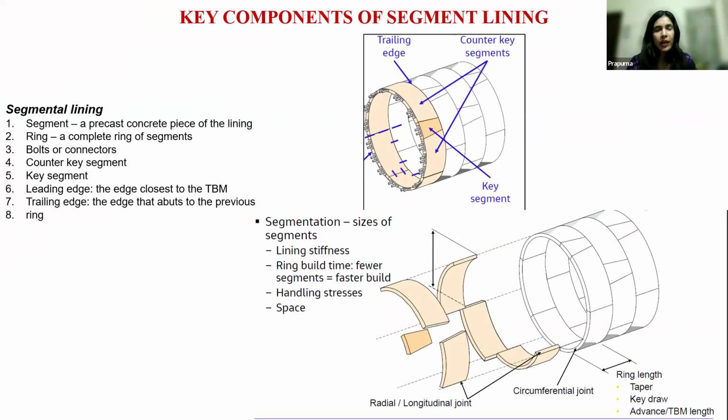Have we used hyperbaric intervention in Indian projects? We use it, but it depends, as I told you earlier. Hyperbaric intervention in Ahmedabad Metro we used in one of the stages, because in that space the ground was very soft. The clay was highly compressible, and we had very high water ingress. And in one scenario, we did the intervention directly under a charge.